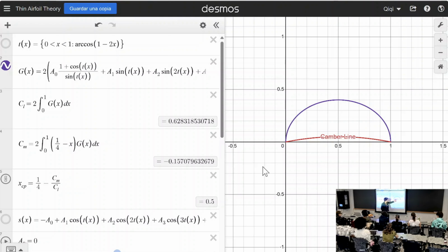And the most important thing about this is that it is symmetric, left and right, which means the center of pressure, the center of lift, is where? Half chord, right? If you get a parabolic camber and pitch it at zero angle of attack, what you're going to get is a center of lift at half chord, not quarter chord. What is the sign of the resulting moment coefficient?